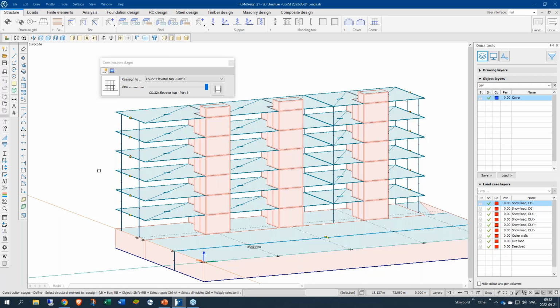And as always, just make a quick test first, rather than to just apply it on the whole structure in the first place. Make a small element or just the small 2 frames that I've shown, just to verify and see what happens if, and apply the loads differently to see what is happening there.